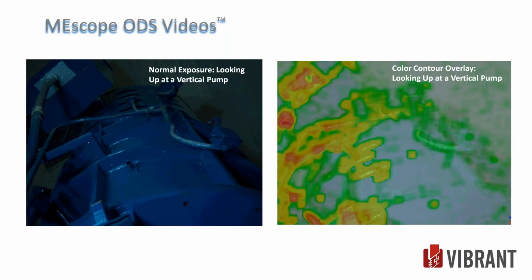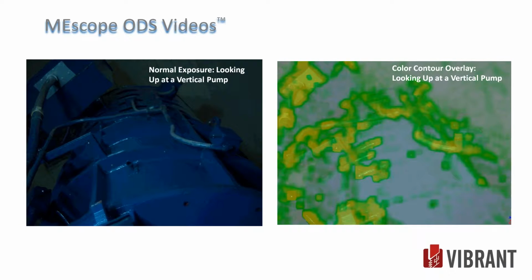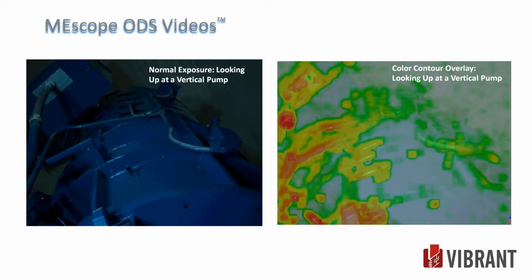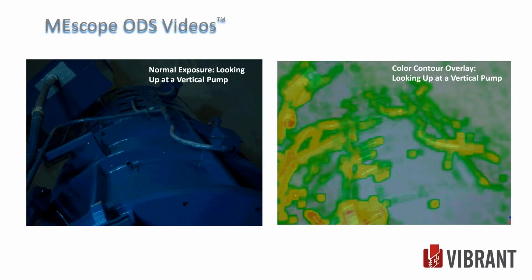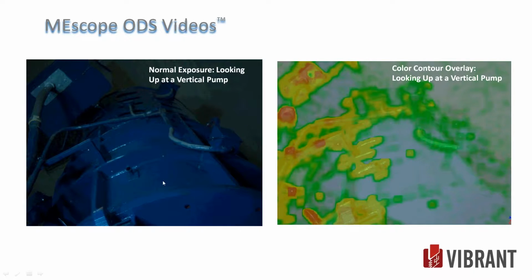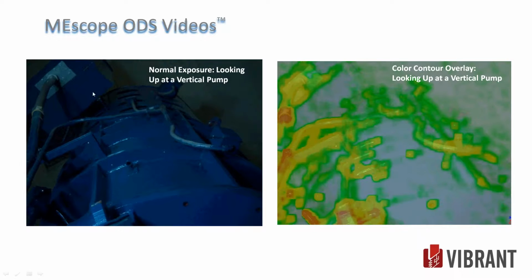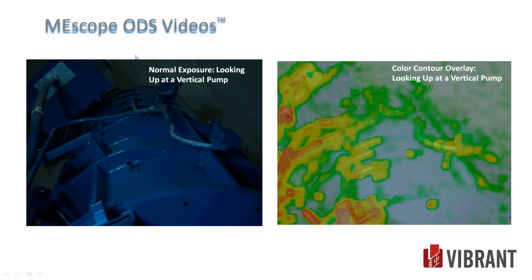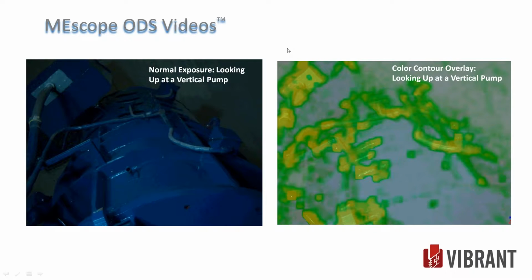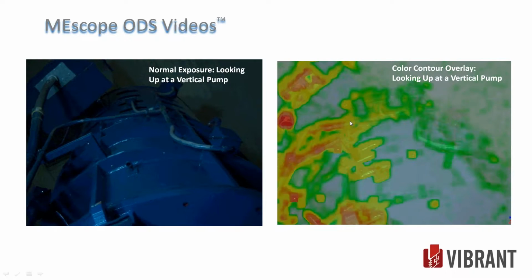Usually you'll have what they call reed modes, kind of like the antenna on your car. As you're driving down the road, it'll go into a certain mode shape. You have one in each direction. So there's a mode shape sideways, like this is looking. This is the electrical box, so we'll go up here. So we have one direction perpendicular to the electrical box, and another one 90 degrees away from that.